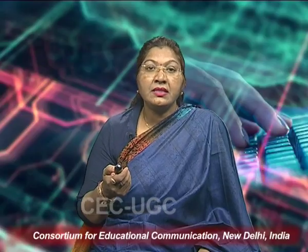In this case, the interaction begins immediately between the RF field, which has very low power, and the electron beam. So there will be an interaction between the RF field and the electron beam. The electron beam is additionally influenced by the alternating field, and the process begins, which is described as a sequence of phases 1 to 4 of the interaction between the RF field and the velocity modulated electrons.